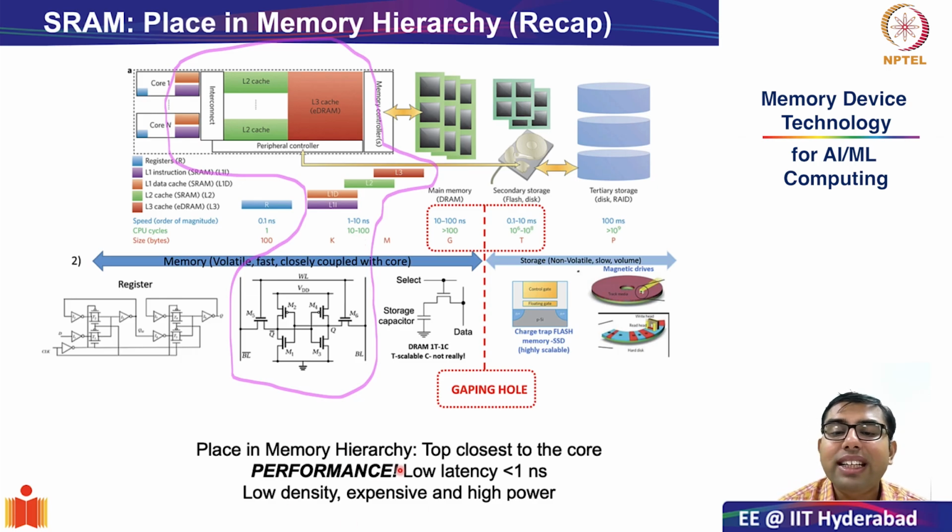Also, we saw that these SRAM cells are quite expensive when implemented along with logic cells. Why is this the case? This is because they are accommodated in the same footprint as your logic transistors. In essence, as we will see, they are made from the same transistor technology which constitutes your logic core. Finally, we also need to worry about the power that these SRAM cells consume, and we will see that it is a significant portion of your entire logic chip's power.